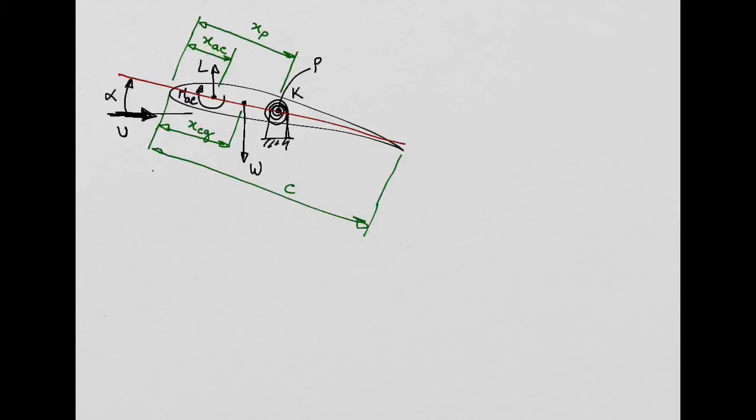One more thing I'm going to introduce, which is going to be new, is that this angle of attack alpha will have two components, and this is very important for you to understand. One is what we call the rigid component, alpha r, which is basically the angle of attack you have been treating in aerodynamics. You are assuming the wing is rigid, right? No deformation of the wing.